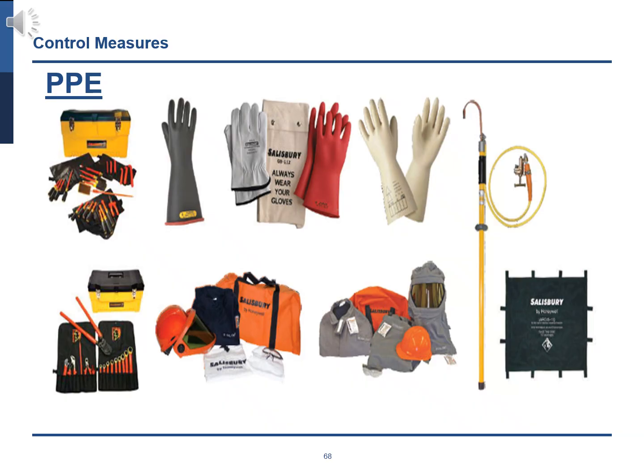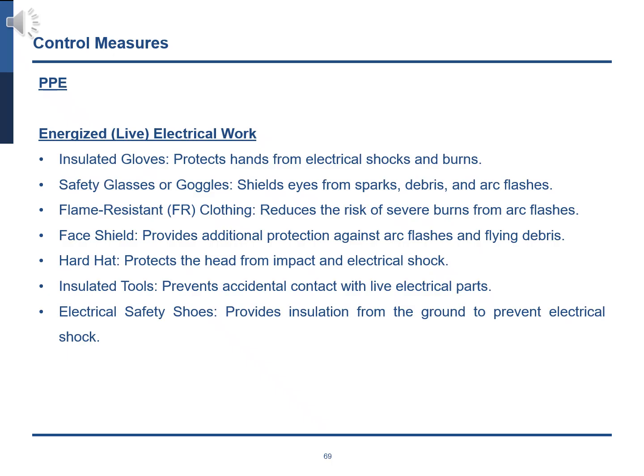PPE. Energized, live, electrical work. Insulated gloves protect hands from electrical shocks and burns. Safety glasses or goggles shield eyes from sparks, debris, and arc flashes. Flame-resistant, FR, clothing reduces the risk of severe burns from arc flashes. Face shield provides additional protection against arc flashes and flying debris.